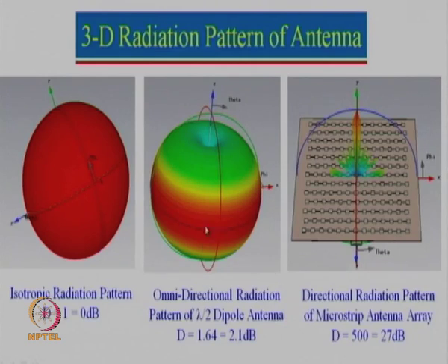So, if the dipole is like this, maximum radiation is all along the dipole antenna, and as we move up, maximum radiation. If we see from the tip, we only see the tip of the dipole, so it is very little radiation here. And in 2D pattern you can think of this whole thing as an 8 like this, and that 8 is getting rotated.